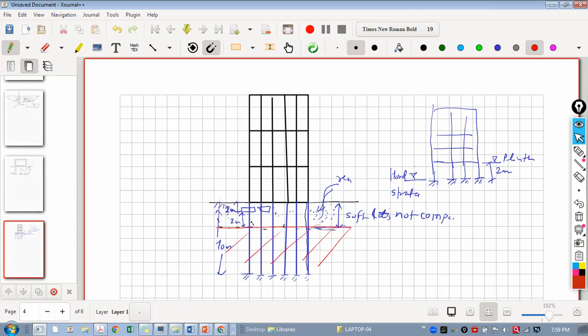And this is soft and displaced or uncompacted soil due to construction activities and the requirement of the pile cap at a certain level, 2 meters, 1 meter, whatever. So I would say take 2 meters or 1 meter below the pile cap. And within the compacted zone, this is the level of support you should take for modeling. Okay, getting this?